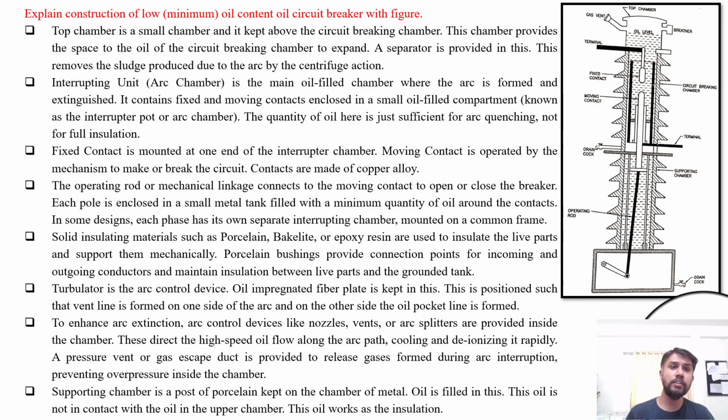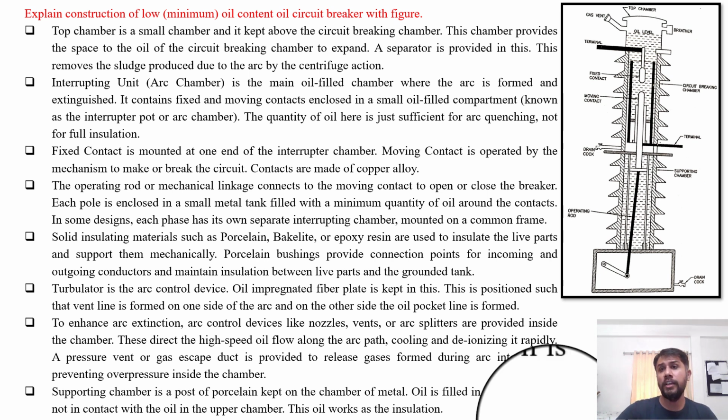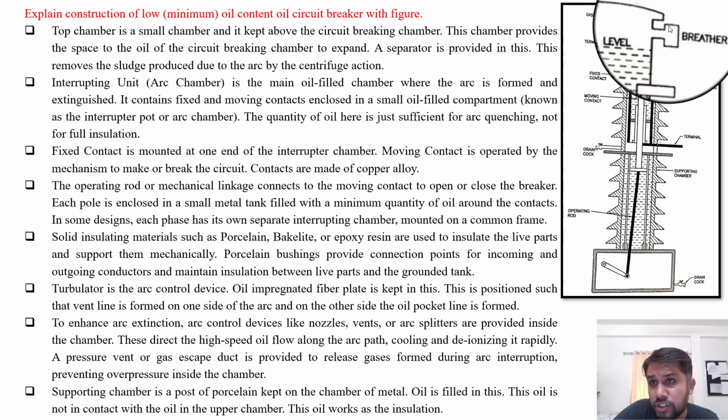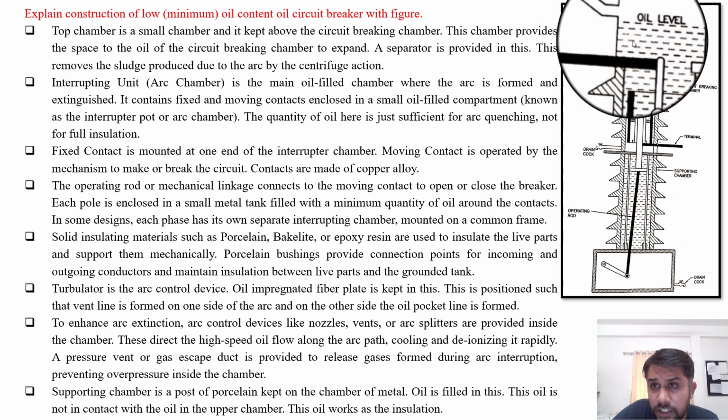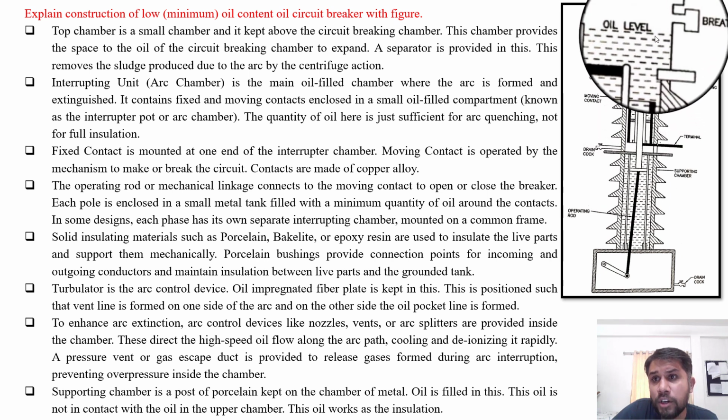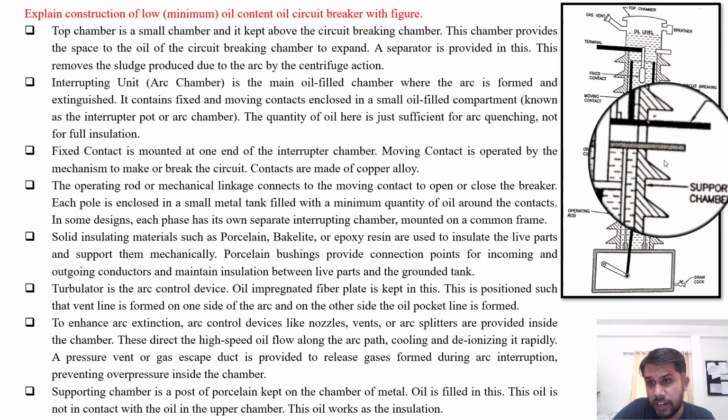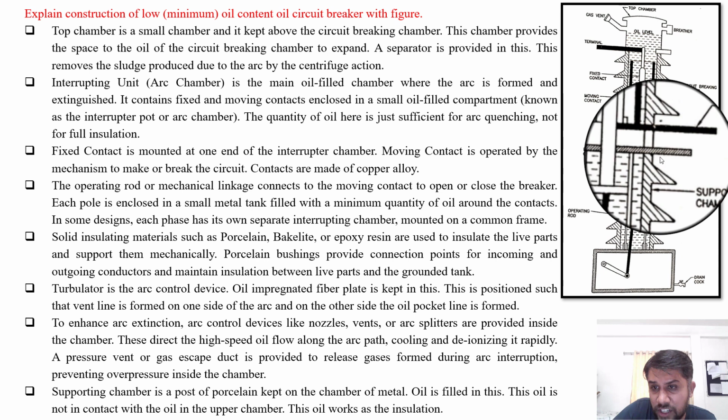Explain the construction of a low oil content circuit breaker, or minimum oil content circuit breaker, with a figure. So in this, here it is. This is the top chamber provided. This middle one is the arc chamber or circuit interrupting chamber, and this last is the supporting chamber.